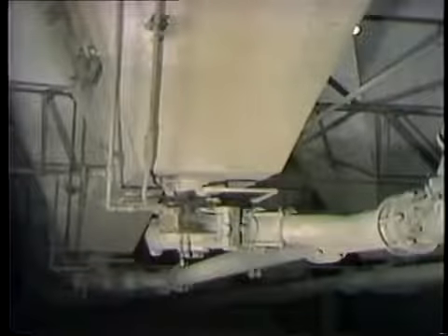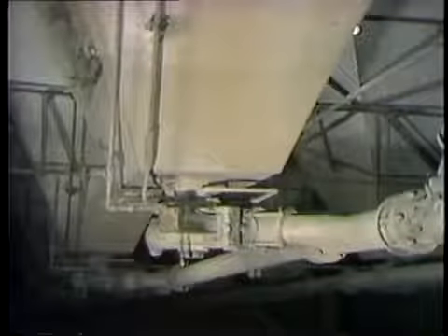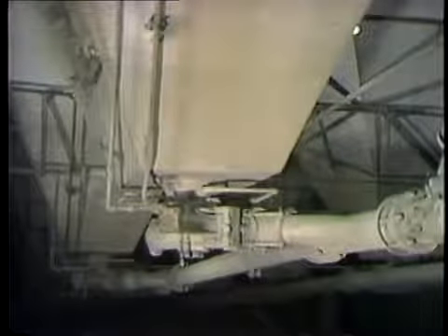However, if steam or water from a leaking tube is sprayed into the gas flow path, it will turn the dry, powdery ash into mud, causing it to stick to boiler tubes. The wet fly ash will insulate the boiler tubes and prevent efficient heat transfer, or it may clog the air preheater. Wet fly ash will also stick inside ash hoppers in the fly ash handling system. If the problem is severe enough, the boiler will have to be shut down and the ash hoppers opened up and cleaned.